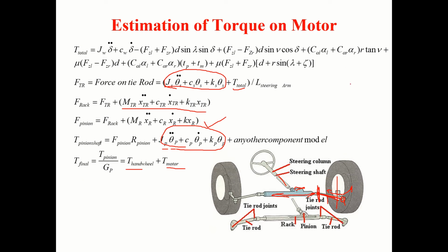Okay, the idea is now simple. First, I can say delta is equal to 57.3 L by R plus K A by BG, lateral acceleration, or we can say V squared by R. I know understeer gradient of the vehicle is known.